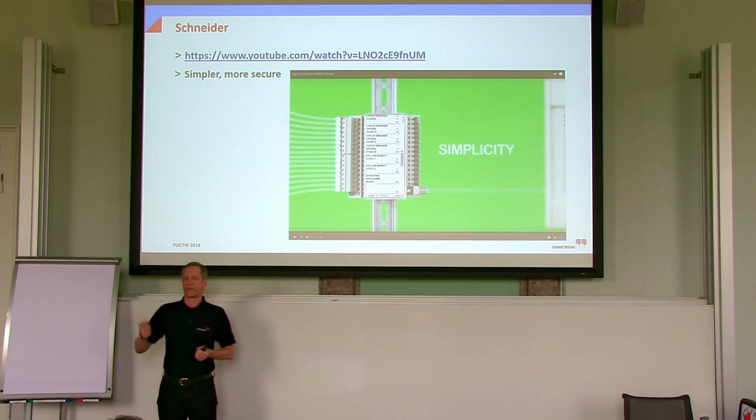And then we made the math. You have so many substations per year, this and that, and then we extrapolated, and we said there are probably in your system more than 100 open wire loops that will not operate when they should.